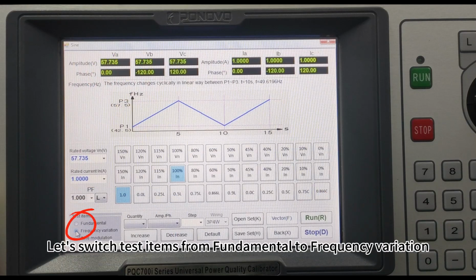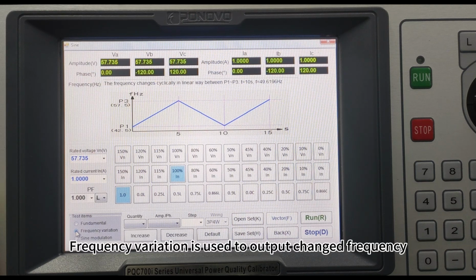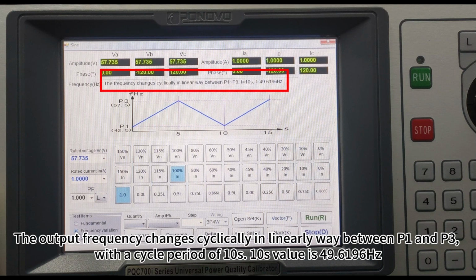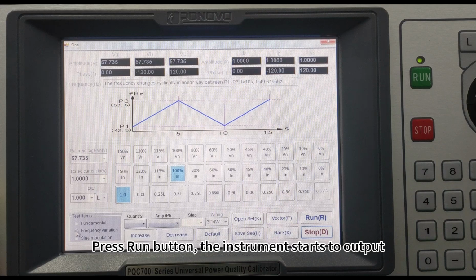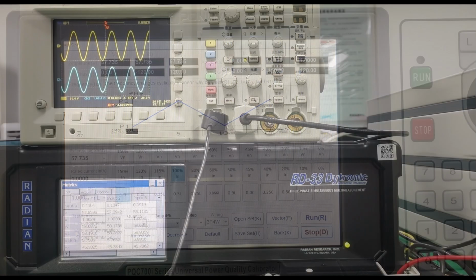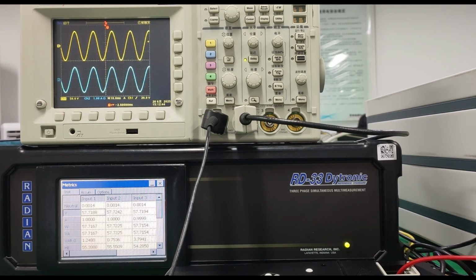Let's switch test items from fundamental to frequency variation. Frequency variation is used to output changed frequency. The output frequency changes cyclically and linearly way between P1 and P3, with a cycle period of 10 seconds. 10-second value is 49.6196 Hz. Press run button, the instrument starts to output. The frequency is changing between 42.5 Hz and 57.5 Hz.